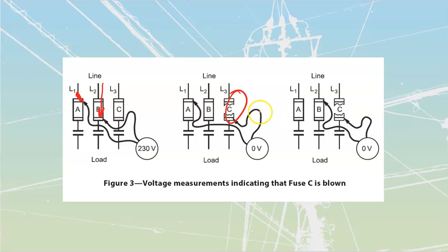What I'll do is I'll double check to the next one here as well. I'm checking my line C fuse over here. So I checked across A, I checked across to the bottom of B. B, I would check across to the bottom of C. This is if I've checked on my lines. C, I would check across to the bottom of A. That would tell me which of these are going to be shot. As soon as I find one that's shot, I'm going to test to the next line. That's what we're doing over here. We're moving our tester over onto the B phase to double check that it's not an issue coming in on this side, which is supposed to be our known good side, but rather that it is an issue off of this side that we have just identified.